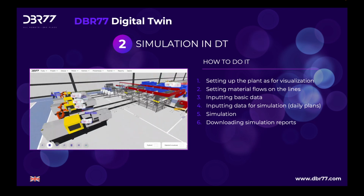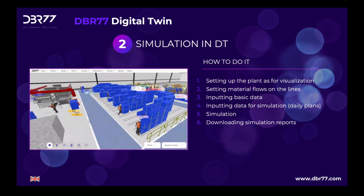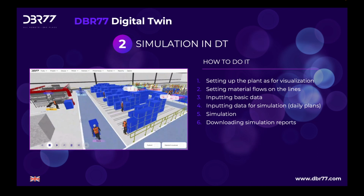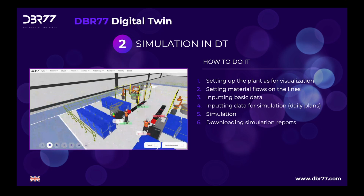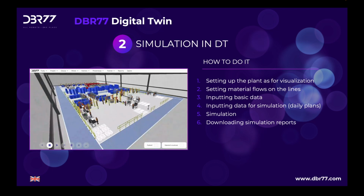This setup includes both the architecture of the plant and the placement of individual elements that reflect the real flow of materials on production lines. The next step is the introduction of basic data, such as machine parameters, cycle times, and available resources. After entering basic data, the stage of introducing data specific for simulations follows, including daily production plans.